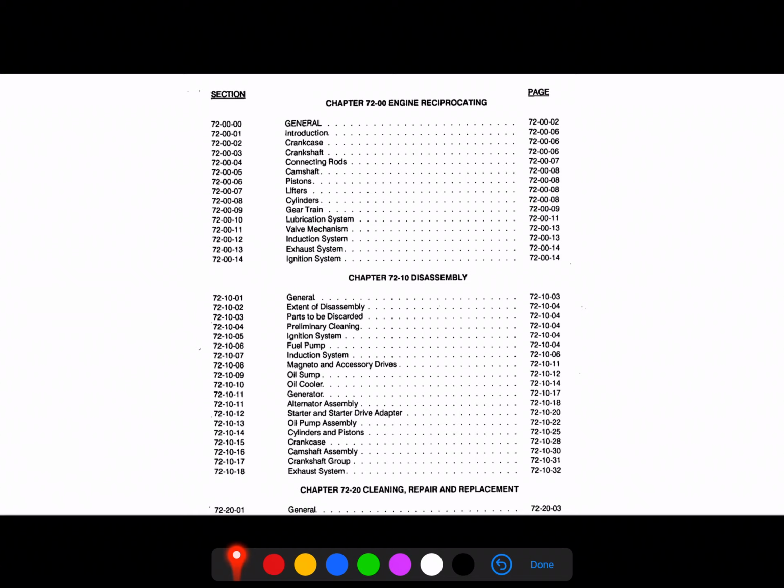The other thing that will happen is a lot of different maintenance manuals will phrase the terms they use in slightly different ways, but it may be different than what you're expecting. So for instance, if I'm looking for a chart for oil selection and I just search oil, then it may show me everything within that PDF that talks about oil. However, the one spot I'm looking for the grade of oil to use may be labeled within the manual as lubricant selection, in which case, if I search for oil, I'm not going to be able to find it.